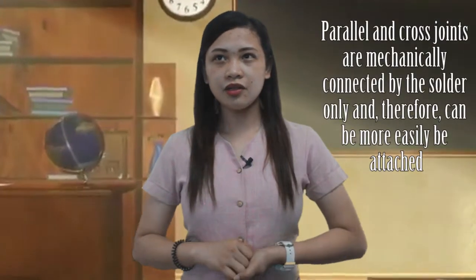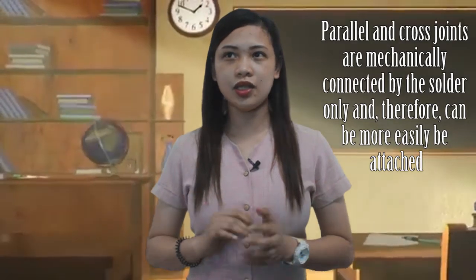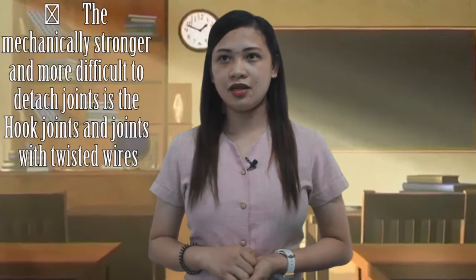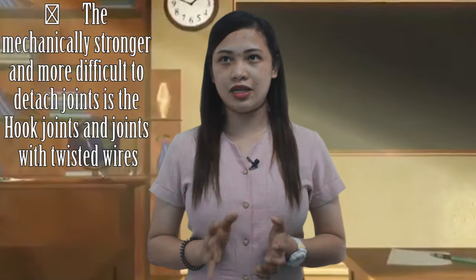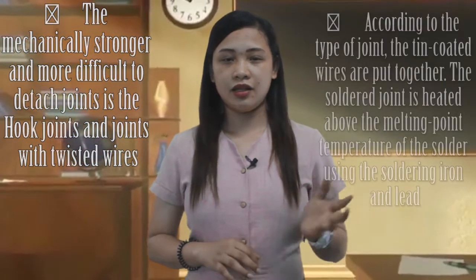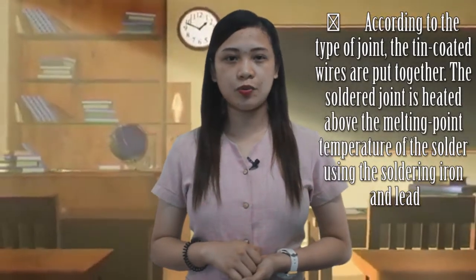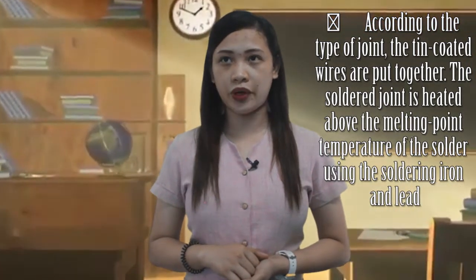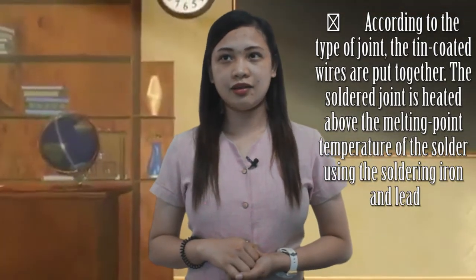Next, the parallel and cross joints are mechanically connected by the solder only and therefore can more easily be detached. Next, the mechanically stronger and more difficult to detach joints are the hook joints and joints with twisted wires. Next, according to the type of joint, the tin-coated wires are put together. The solder joint is heated above the melting point temperature of the solder using the soldering iron and the lead.